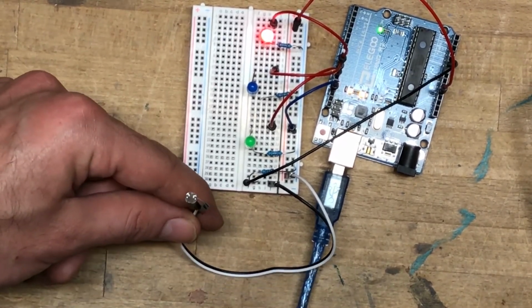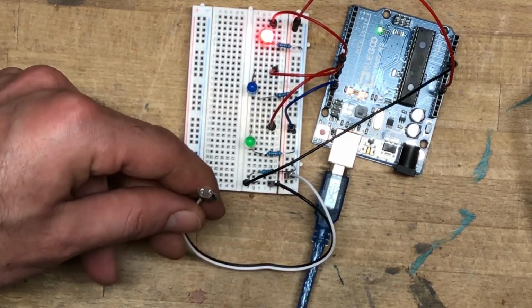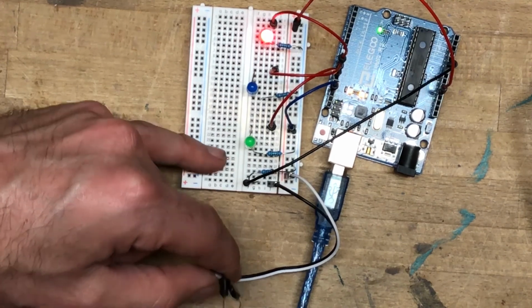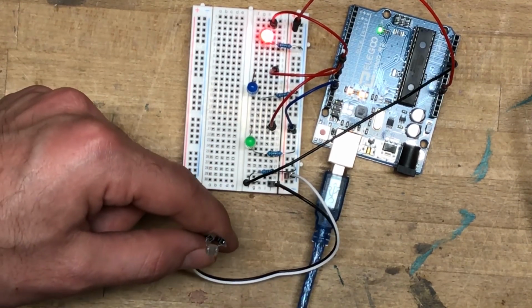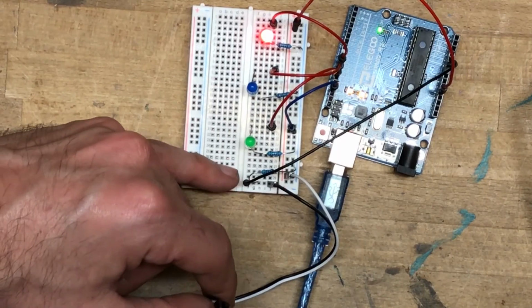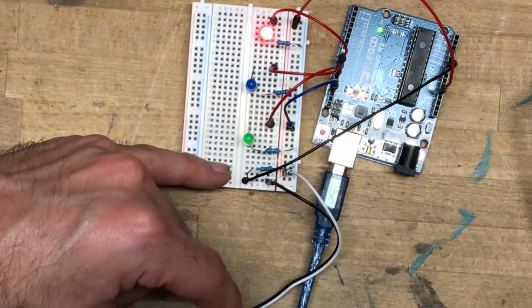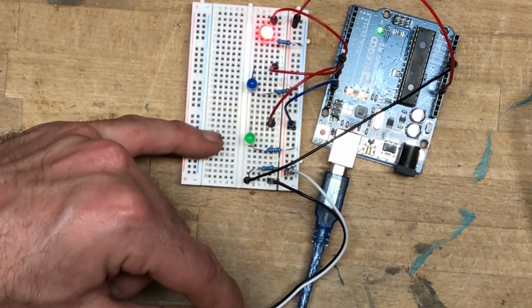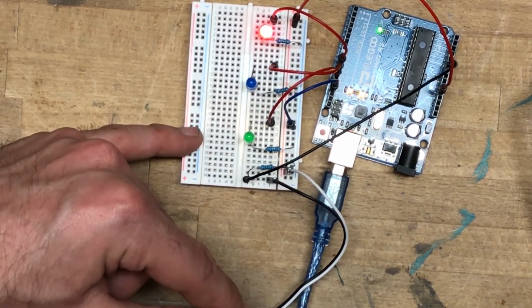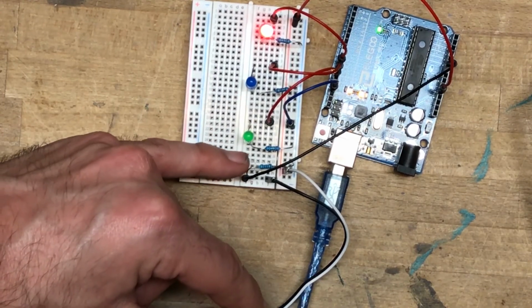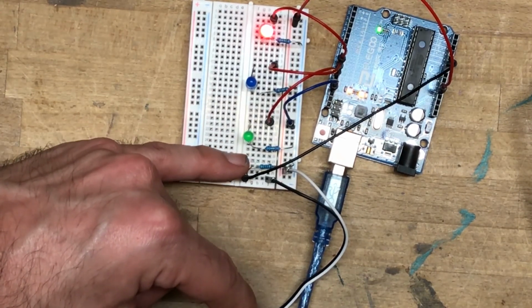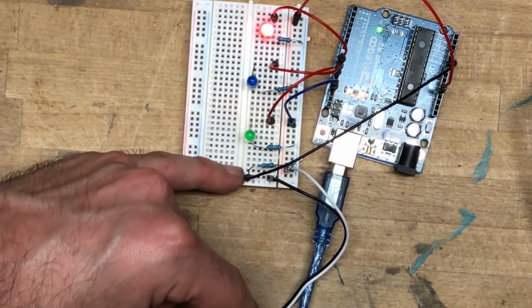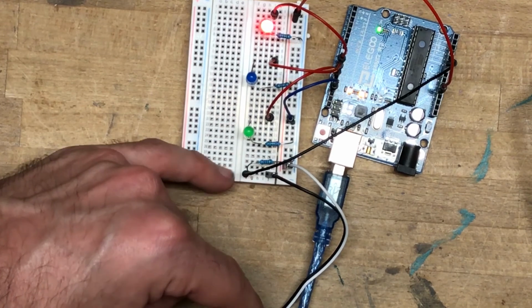Alright everyone, so we've got our circuit hooked up with our light dependent resistor. We've got this secondary resistor making a voltage divider with this one. I'll explain that next week. Needless to say, this last row shares one leg of both the light dependent resistor and the regular 5K resistor. One leg of the light dependent resistor is going into positive, one leg of the static or just regular resistor is going into negative, and we're going from that same row, the last row, back to pin A0 on the analog side.